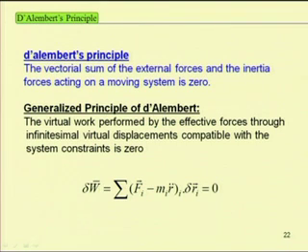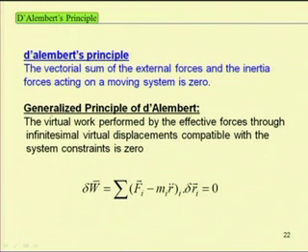After we convert this dynamical system to a static system, we can apply the virtual work principle, which is then known as the generalized principle of D'Alembert. The effective force is nothing but the summation of the external force and the inertia force. So, this term is the inertia force. The virtual work done by this effective force is equal to 0.